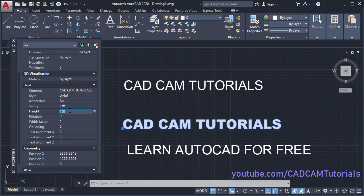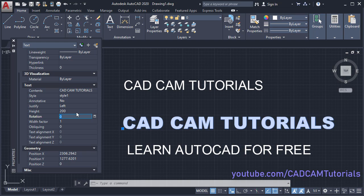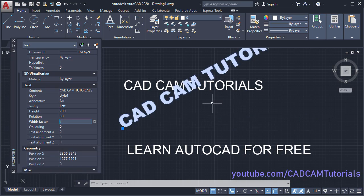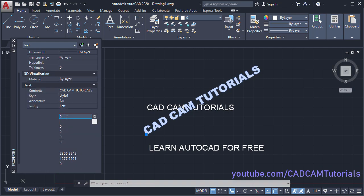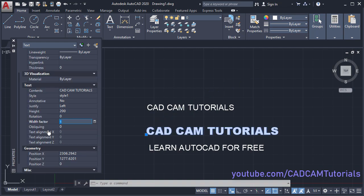Then from here you can change height. Suppose I want 200, enter. Then rotation angle, suppose I want 30 degree, enter. So it will get rotated like this. I will make it 0, enter. So it will get horizontal.